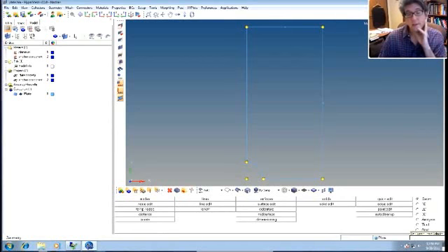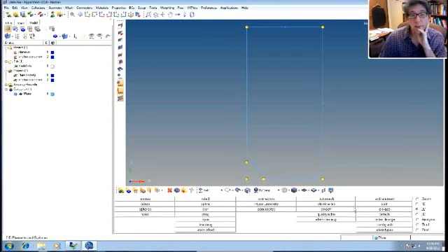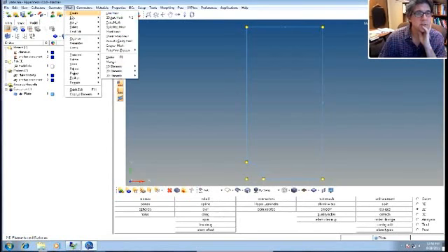Now we're ready to mesh. Actually, we don't have to create a surface to mesh. Hypermesh will automatically do it for geometry that lies in a plane with just the boundary lines. So if you have geometry that's fully in a plane, you can just draw the lines that bound the surface. Then if you go under 2D, the radio button that gives you the options for doing 2D meshes, or under here I think it goes under mesh. It's a little different here. Here it puts everything together, so you have to do mesh.